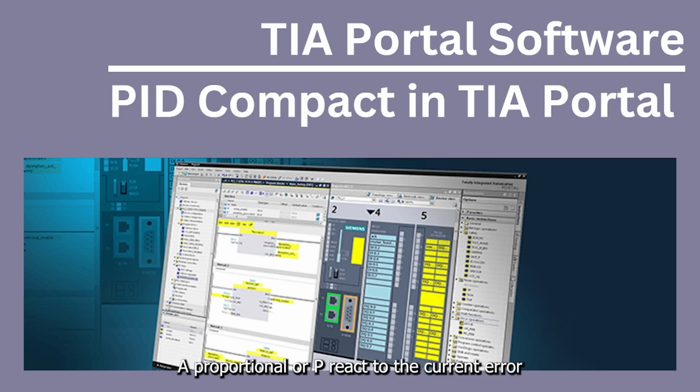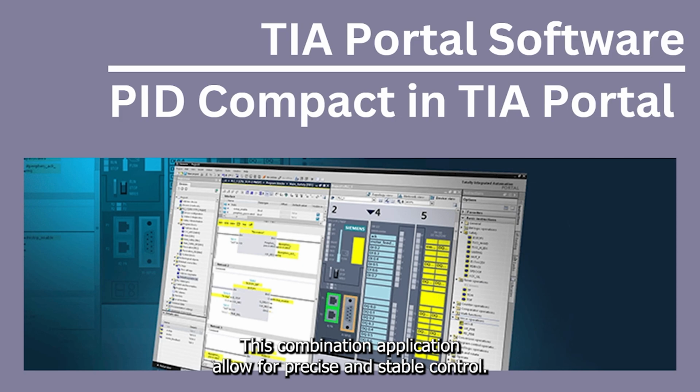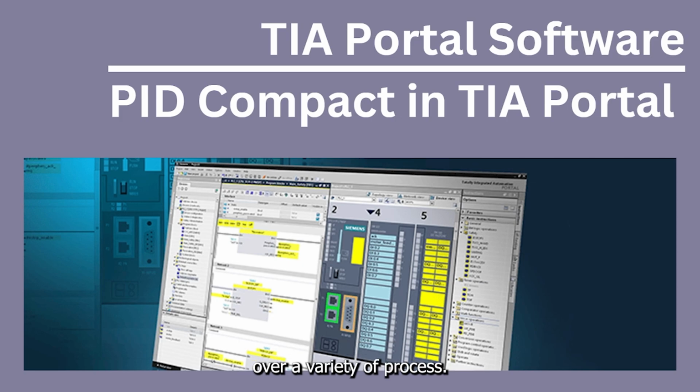A proportional, or P, reacts to the current error. An integral, or I, reacts to the accumulation of past error. A derivative, D, predicts the future based on the rate of change. This combination allows for precise and stable control over a variety of processes.